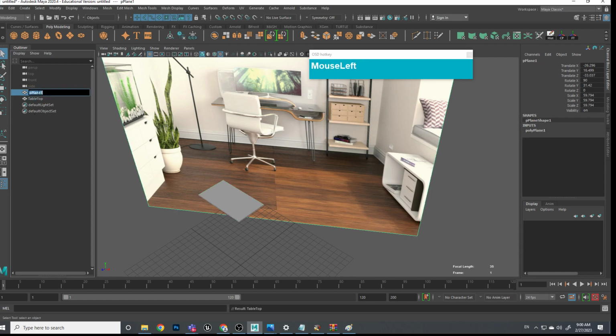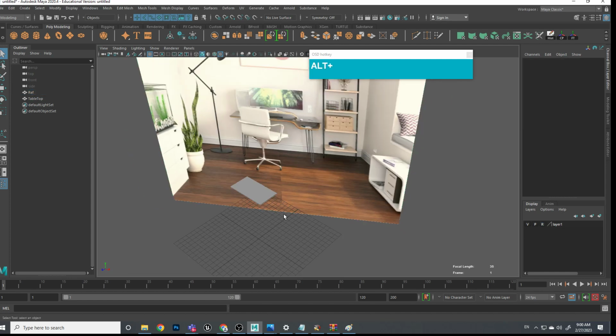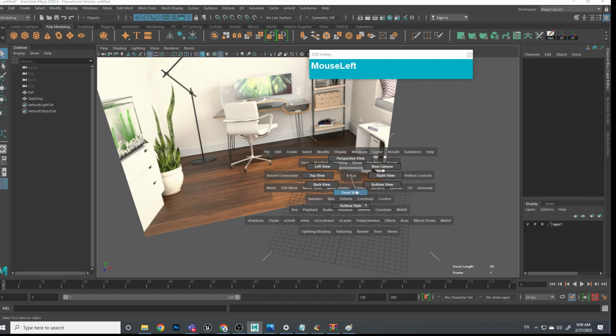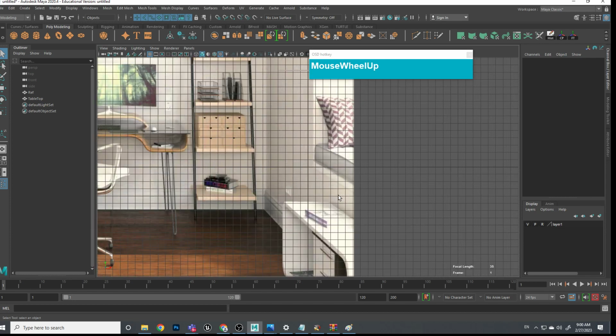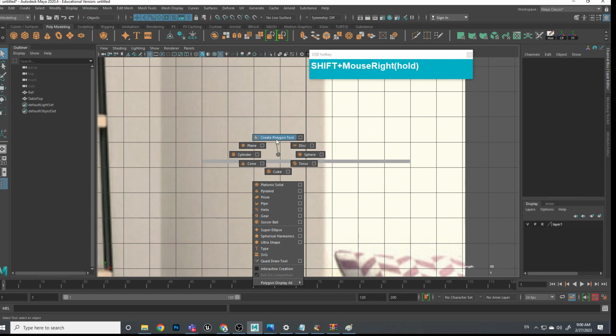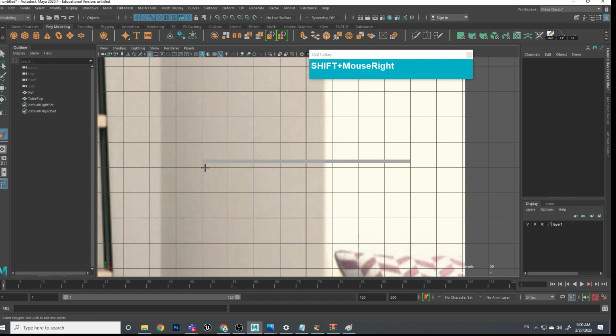My reference will be my reference. I want to put my reference inside its own layer and lock it so that I will not accidentally select it. Next will be the profile here. It looks like just a curve to be extruded. So I'll go to the front view, and then this is my table. So I'll use the Create Polygon tool. I'll start off by creating two straight lines here, then a bottom curve here like that, then upper like this.